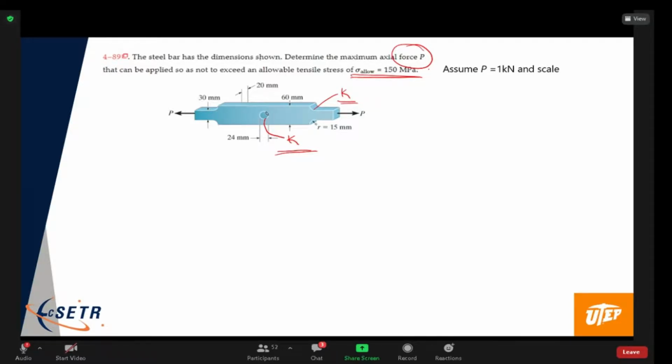So we could use those calculations and figure out that the stress max at the hole equals K times the stress average at the hole. But this is going to require P, and then we could figure out that the stress max at the fillet equals a different K, I'll put an H here and an F here, because they're going to have different values.